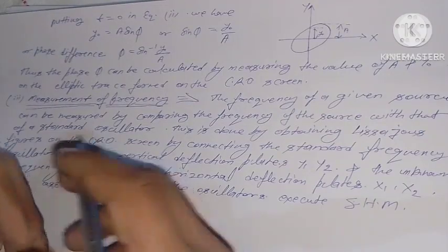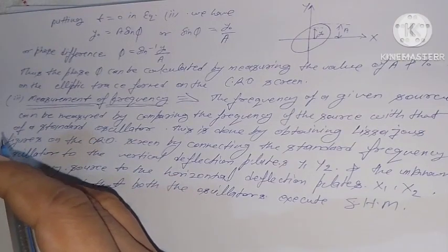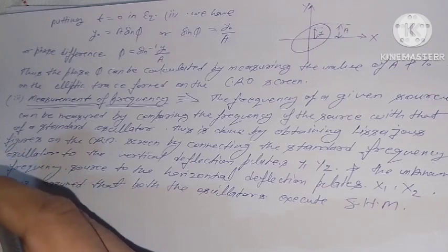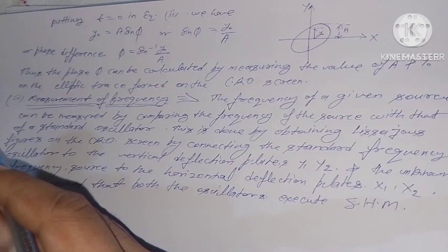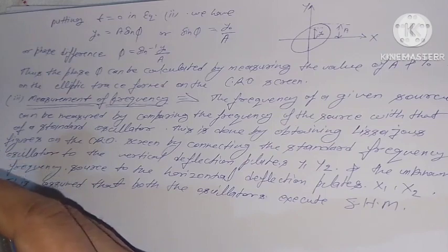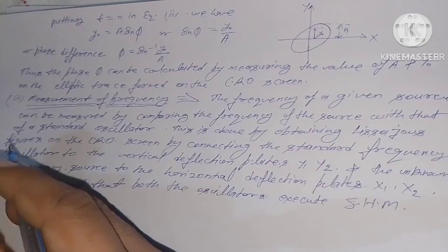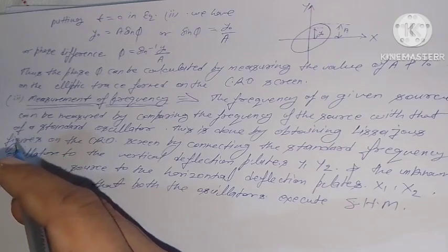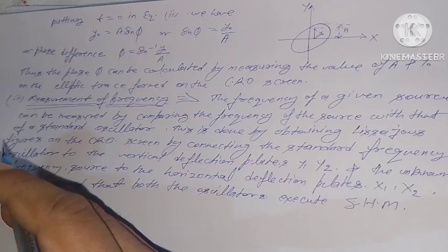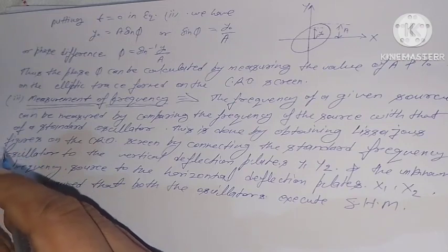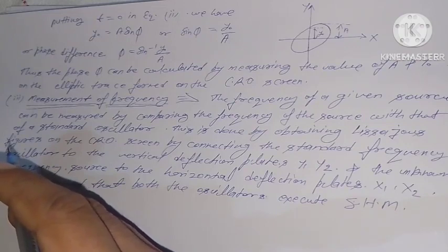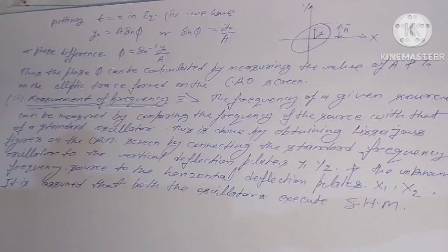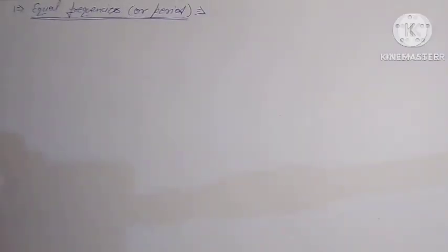Since simple harmonic motion plotted against time gives a sinusoidal configuration, two sinusoidal electrical inputs to a cathode ray oscilloscope will give a Lissajous pattern on the screen. The exact pattern traced out, the nature of the resultant path, depends upon the frequency or period, amplitude and phase relationship of the two inputs. First, equal frequencies or periods.